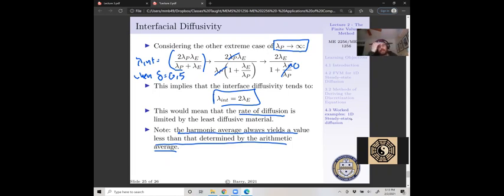So the harmonic average has pros and cons, and we have to be very careful when we do this type of averaging. Really, the logic you have to put into your system is not setting, say, j equal to 0 at certain instances. It's which averaging technique do we want to use when. For a situation of a specified non-zero flux, the arithmetic average is great. But if you do have an insulator, we have to use our harmonic averaging.